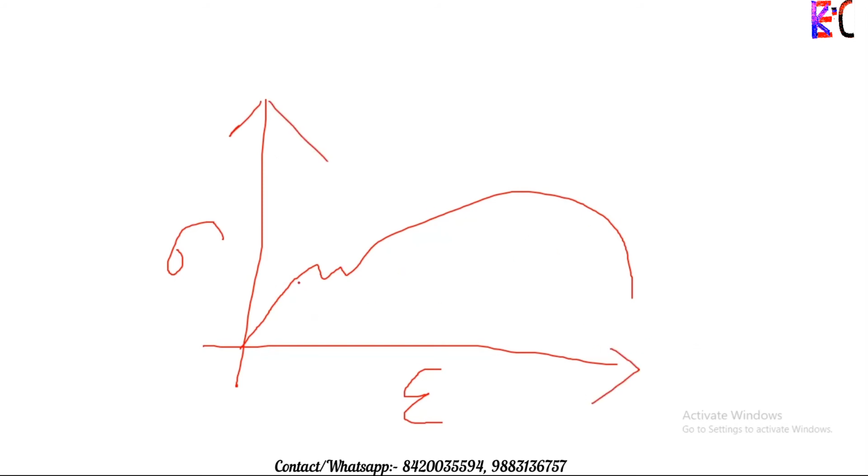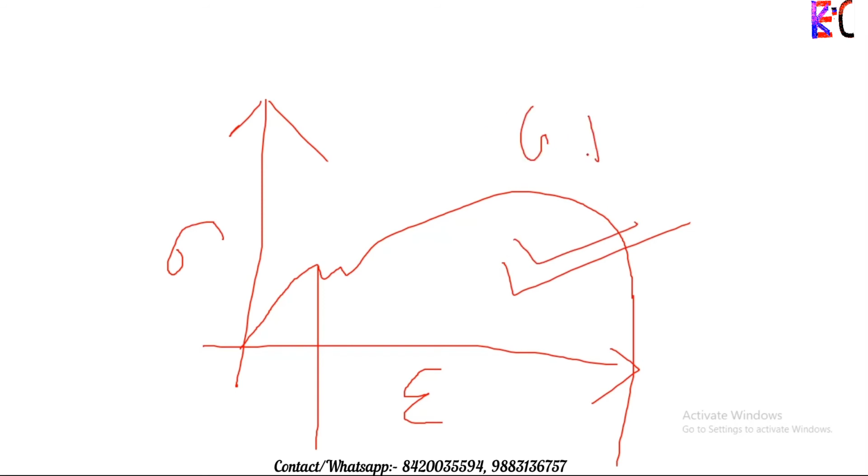Fine. So this is the elastic limit and this is the plastic limit. So Gerber and Goodman, G plus G, work over here, and Soderberg works over here. That means Soderberg's equations and everything are valid till this one.